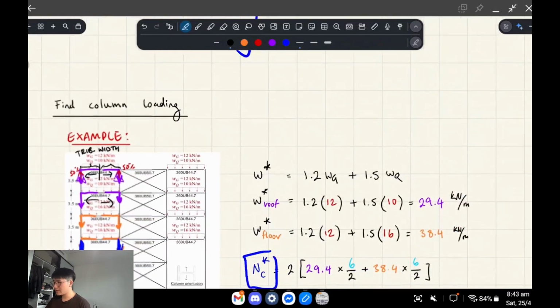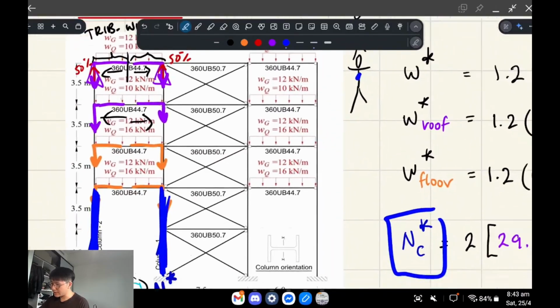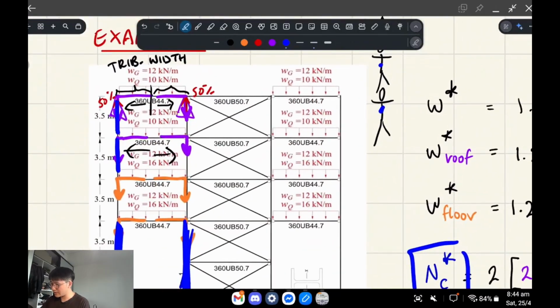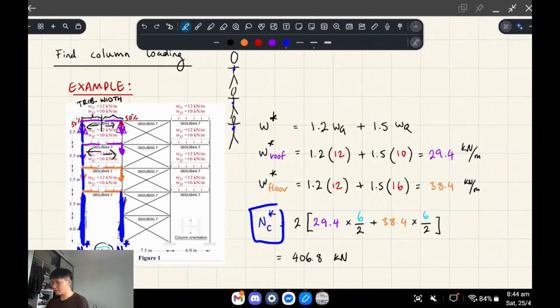The way that I've been explaining this to my first and second year students is, imagine a stack of children, and they're all giving each other piggyback rides, right? The dude at the top only has to account for his own self-weight. The guy underneath has to carry the dude on top's self-weight and his own, and the guy at the bottom carries all three of their self-weights. So this is important for columns because each level of the column has to carry the load of the levels above it. At the very bottom, you have the most axial compression because you have all the loads from the previous floors stacked up and added on, okay?